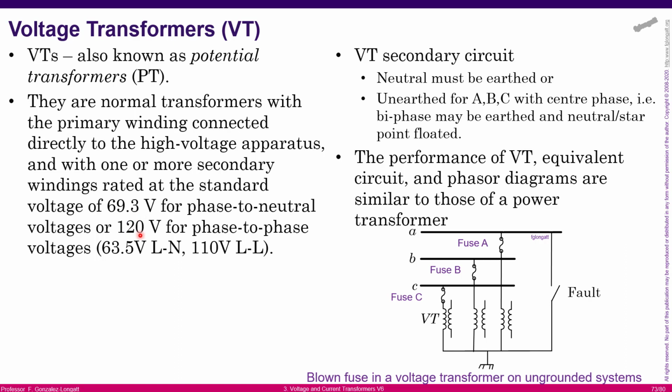Typically with VT transformers, the neutral point must be connected to the neutral point. Okay, or there are some cases where we don't use the neutral point and we keep the neutral point floating. That is the case when we are working with VTs connected in open delta connection, for instance. Okay, where you want to take measurements between two different phases in a three-phase system, but using two voltage transformers. Okay.